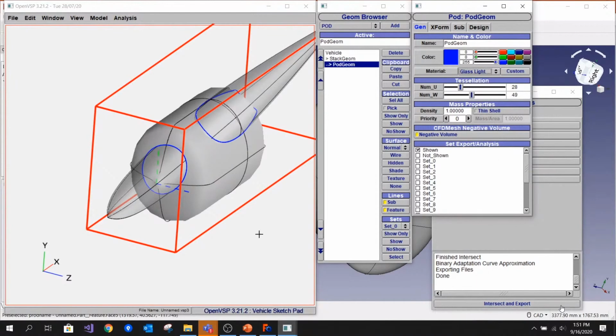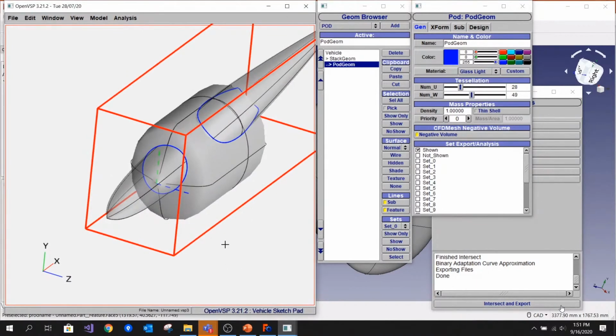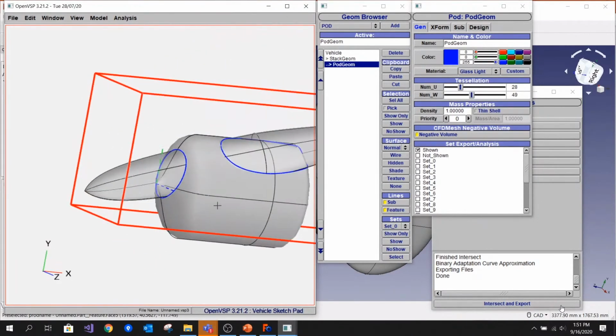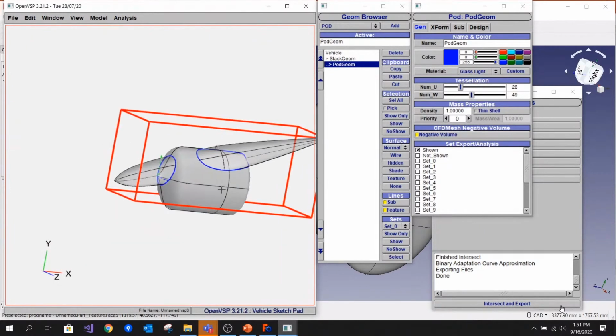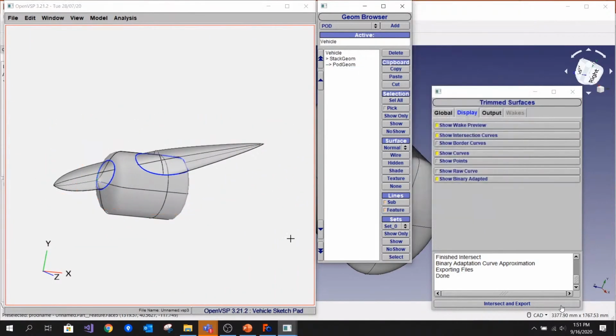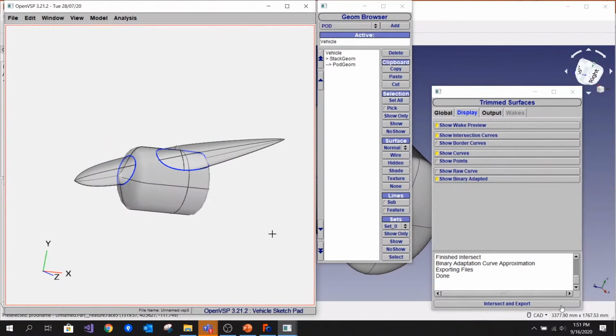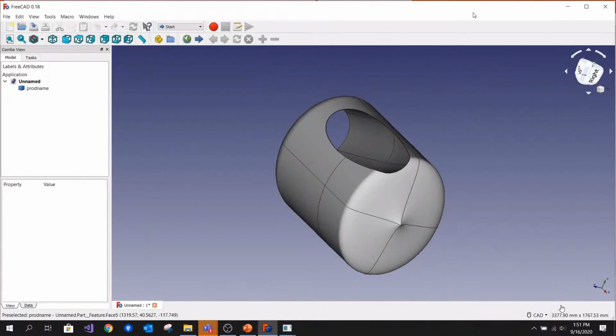When we visualize the surfaces, the solid, the full pod and the other body, those are untrimmed surfaces, and so the wireframe you see on screen is easy to generate because we run from beginning to end on everything. If you think of it like a blanket, and we just run from 0 to 1 in U and 0 to 1 in W, we can traverse the whole thing. And then we have a wireframe and it's easy to visualize.